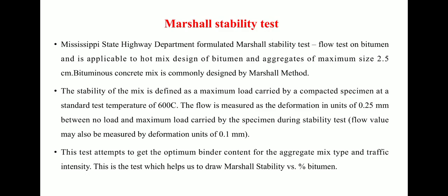size 2.5 cm. Bituminous concrete mix is commonly designed by the Marshall method. This is very important. Bituminous concrete mix is commonly designed by using the Marshall stability method. The stability of the mix is defined as the maximum load carried by a compacted specimen at a standard temperature of 60 degrees centigrade. The flow is measured as the deformation in units of 0.25 mm between no load and maximum carried load by a specimen during the stability test.